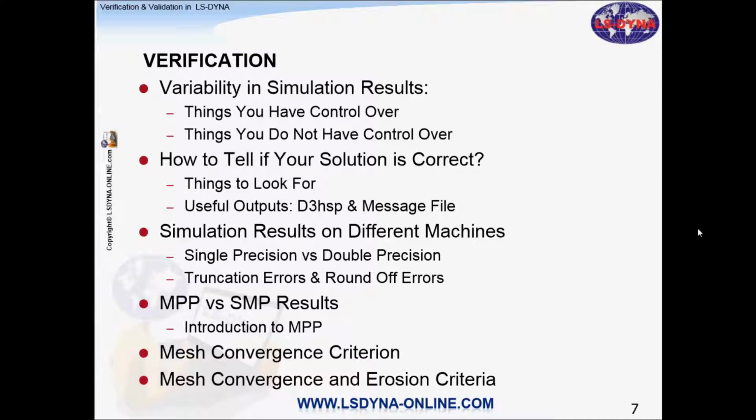Then, how to tell if your results are correct. What are the things to look for in the simulation? This becomes especially important when there is no experimental data. There are some useful outputs that you can take a look at, for example, D3HSP and the message file.